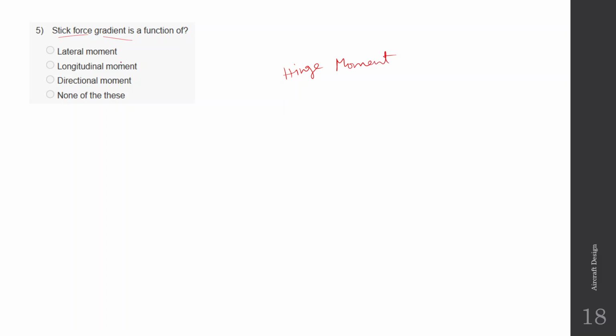It is not a function of the aircraft moments, but it is a function of the hinge moment, and the hinge moment is the torque acting on the hinge of a control surface. So if I consider the aircraft elevator like this, then the elevator has a hinge like this. The moment along this elevator hinge is the hinge moment, and the stick force gradient depends on this hinge moment.